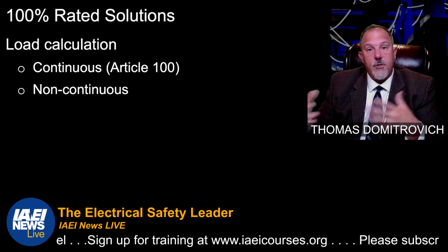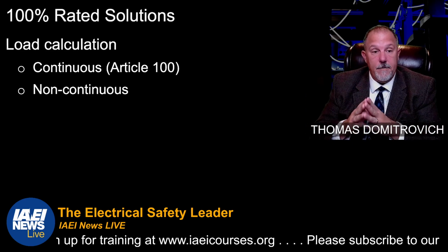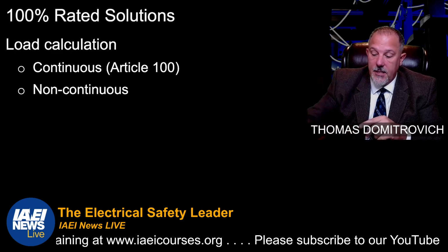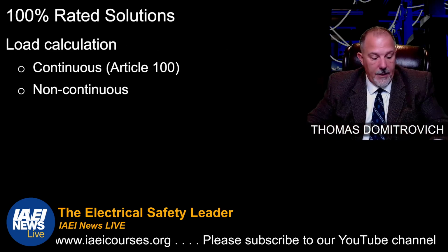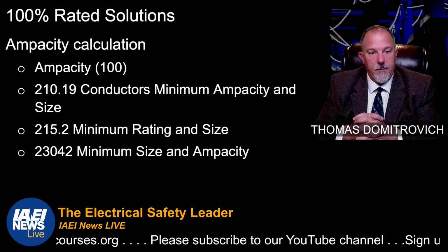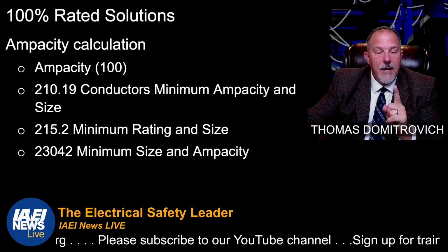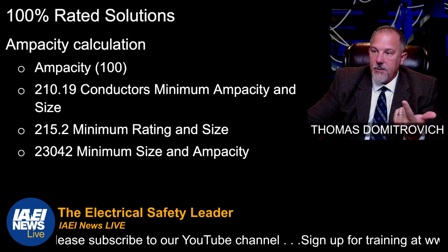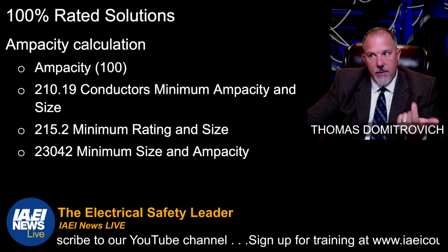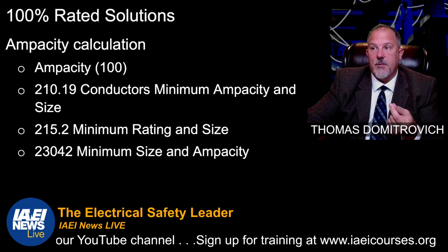Are they continuous or not? Then you make a decision based on that, right? And when you make that decision is when you are calculating the ampacity of things like conductors or busway, right? So let's take a look from an ampacity perspective.